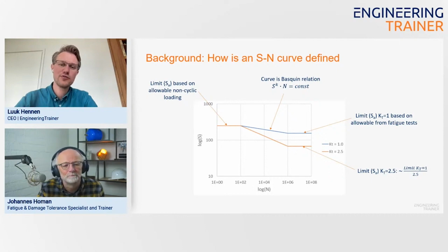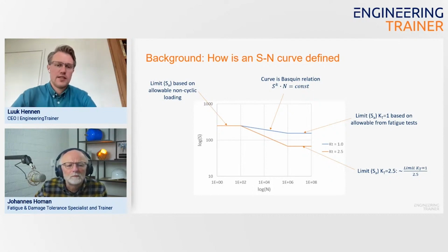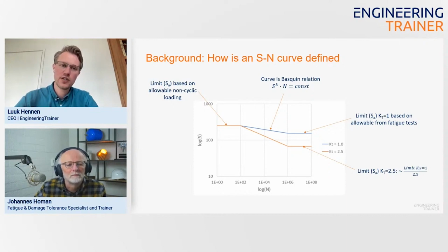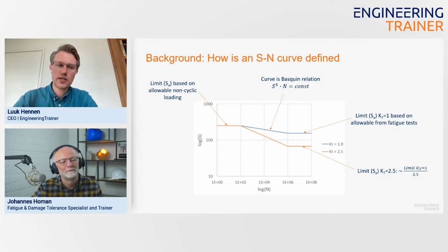All right, it's a bit hard to see due to the log scale, but it's definitely true. Another question about this. We're looking at the stress limits versus the number of cycles, or at a certain number of cycles. At the upper stress limit, so at low number of cycles, on the left of the curve, the stress level is well above the yield strength. How is that typically handled in this SN curve?